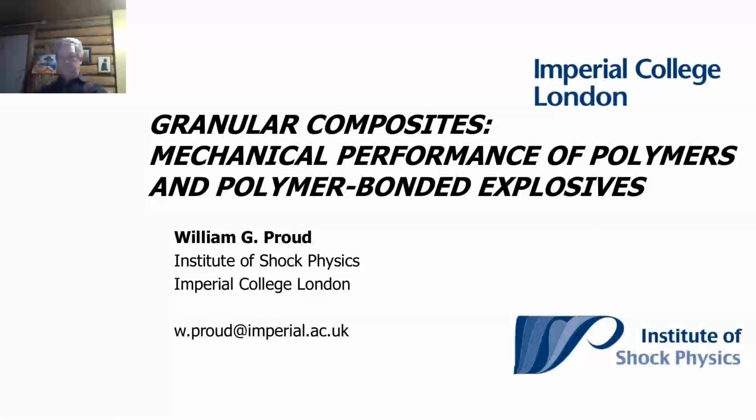But it is non-uniform. Frankly, it's a non-uniform stress and strain field in that Brazilian sample. It's not homogeneous across the sample in any way. I'm talking about the previous slide with the ordinary split Hopkinson bar test.